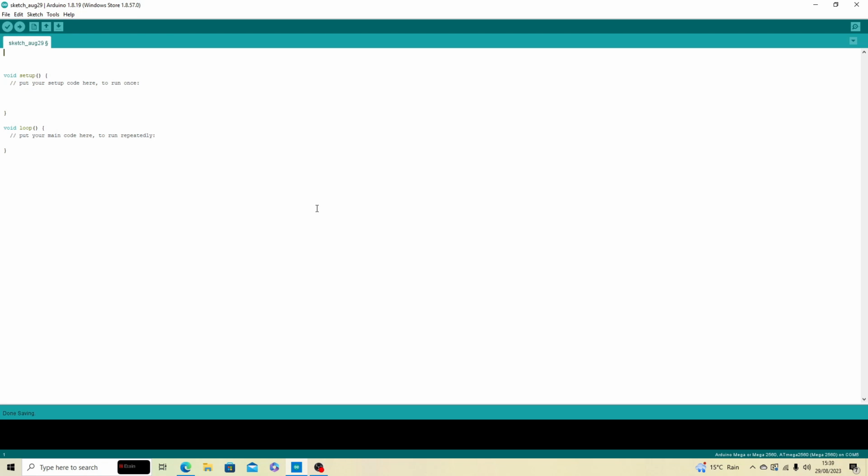Final thing is we're using the ALE signal from the processor, as when that goes high to say there's an address on the pins, then that's when we can monitor the pins output. That's because the pins both share the address and data lines, so I need to use the ALE signal to see when the pins are an address.